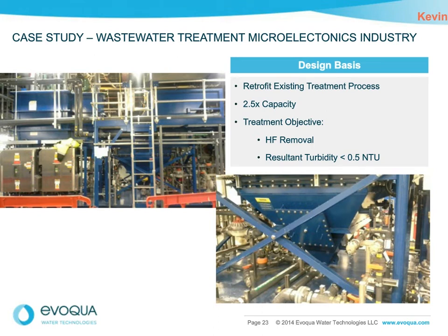The turbidity from the clarifier effluent resulted in an NTU of less than 0.5, which was much better than the effluent from the original wastewater treatment system.